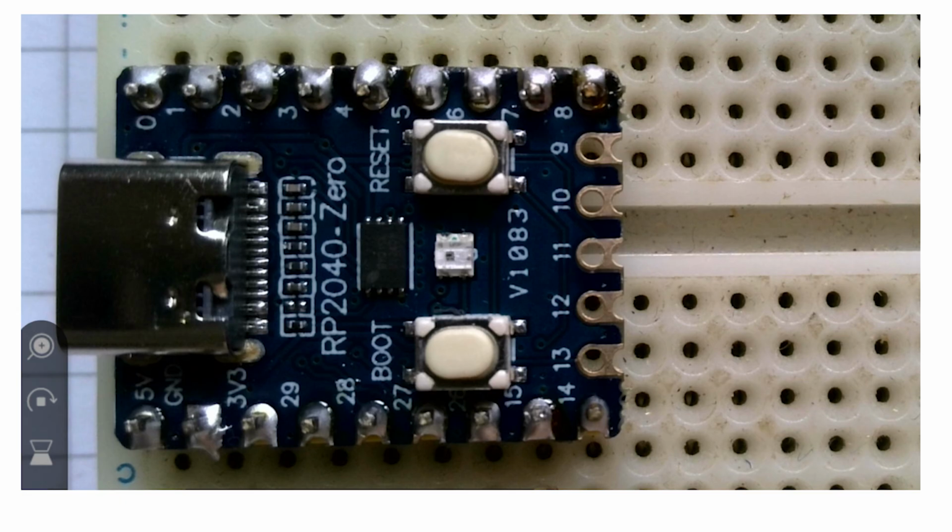But before I do it, to get the software to work, I just say to the software, instead of going to pin 18, go to pin 16. And when I send it to pin 16, the NeoPixel on the board does its thing. And so I can see that the software's working, independent of the hardware.